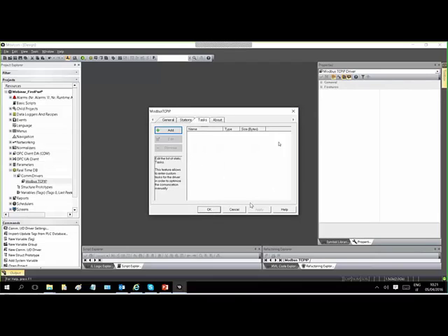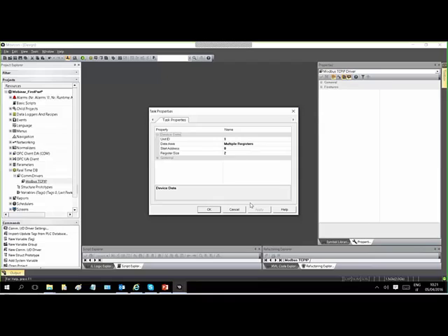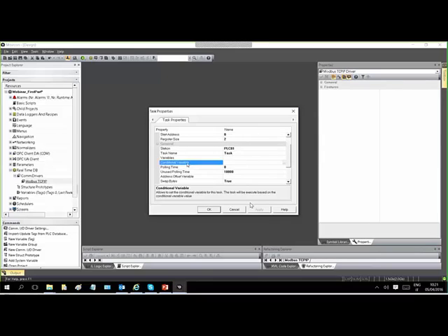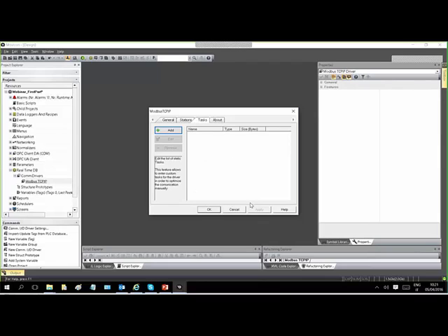Task is not so much used now, because Movicon works with dynamic tasks defined at the variable level. So it's normally not used in this part. Just a few words on what the static task means. You can add and configure your static task here, where you define the data area, the start address, and which variable is changed in this task. The static task offers the possibility to set for each task a predefined polling time, so you can exchange this group of variables with a polling time that could be different from one task to another.